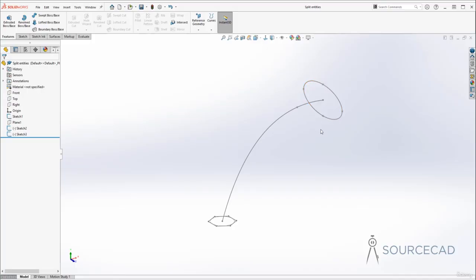And if you try making a loft, of course you can make it for sure, but you won't have better control over the points which are going to connect from this segment to this. Now, if you want to control the way this loft is created, then you can first divide these kinds of segments into an equal number of parts, and then later you can connect those points.